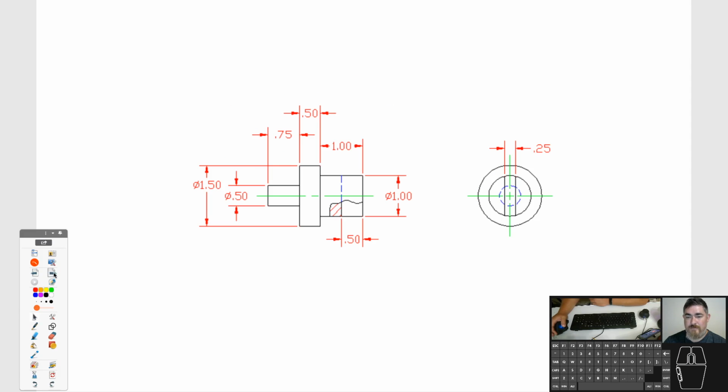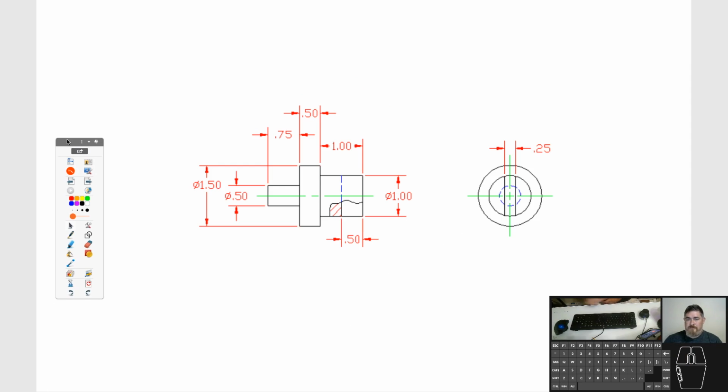And let's move on to the next one. So we have this piece here. So it's a round piece. How are we going to do this? Because it's stacked like this, it's easy to do as 3 cylinders, right? I could do a 1/2 inch cylinder, 3/4 inch, then create a new sketch here, another circle, diameter that, extrude it that far, then another circle, diameter that, extrude it that far. If the dimensions are stacked like this, that's easy to do.